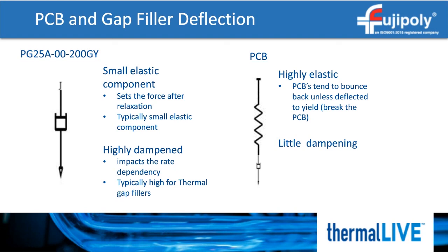The dashpot represents the viscous or rate-dependent component. When we discussed gap fillers earlier on in the webinar, we talked about relaxation and how the speed at which we compress the gap filler will impact the stress created. This is represented by the dashpot. A single dashpot and spring, as seen here, is a Maxwell model, but there are other models that use the same dashpot and spring model.